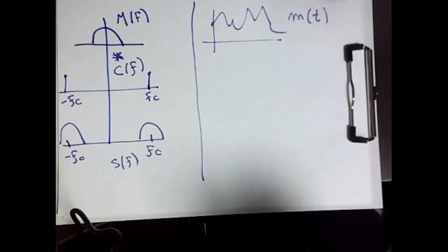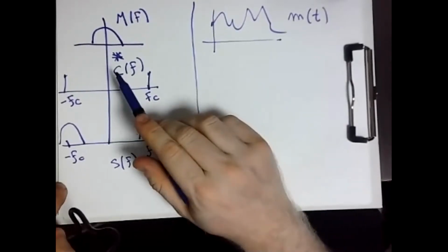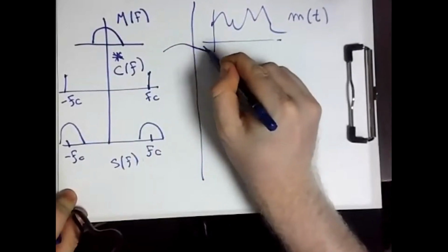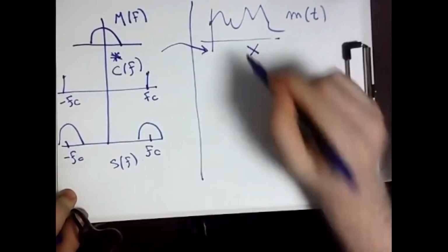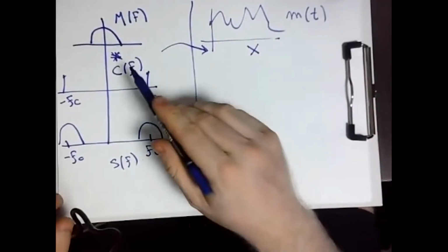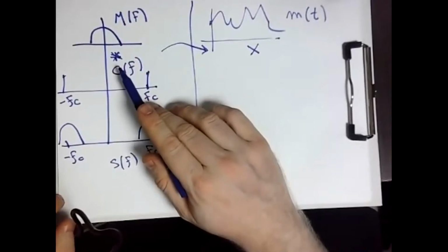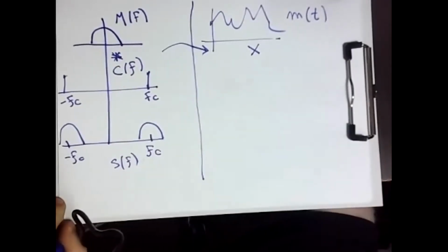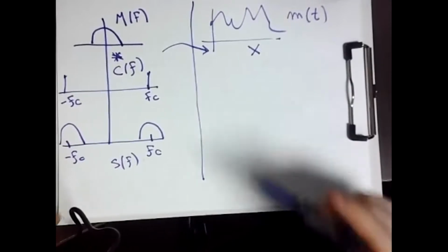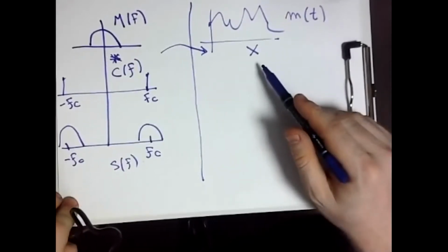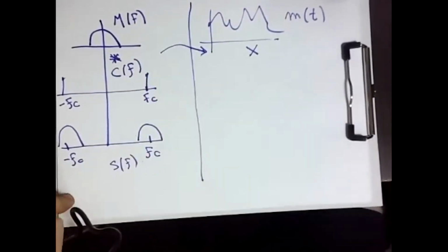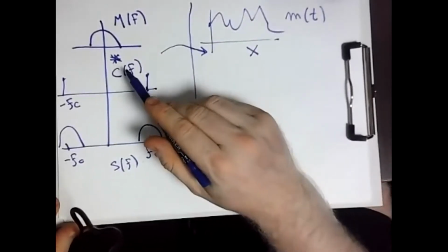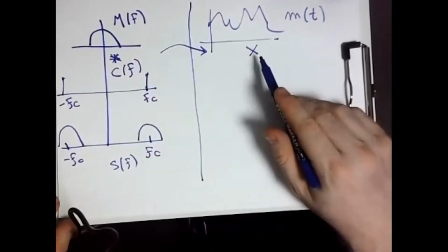remember, the last part of our chapter number 1: convolution in one domain is a multiplication in the other domain. So please don't forget, here we have a convolution in the frequency domain, so we have multiplication in the time domain. In our previous chapter, we did it the other way around. If you remember, we had a multiplication in the frequency, so it becomes a convolution in time. Now we use the reverse direction. We have a convolution in the frequency, so we have a multiplication in time.